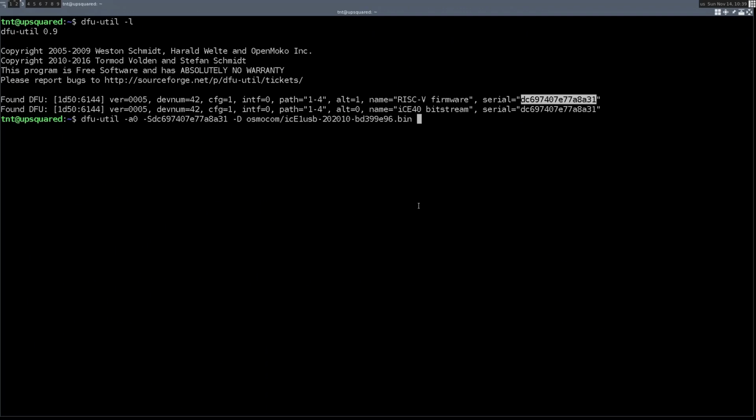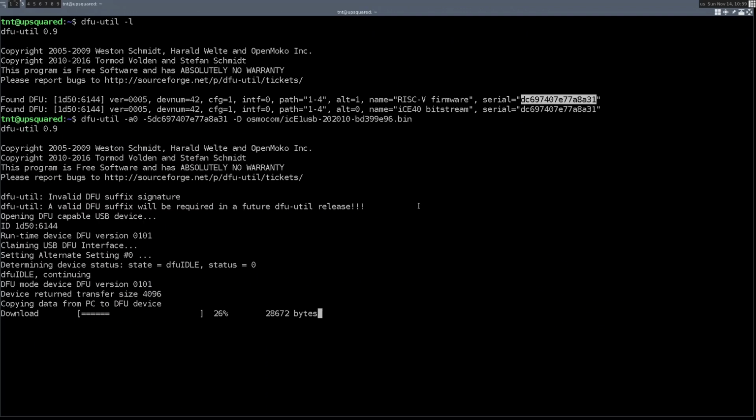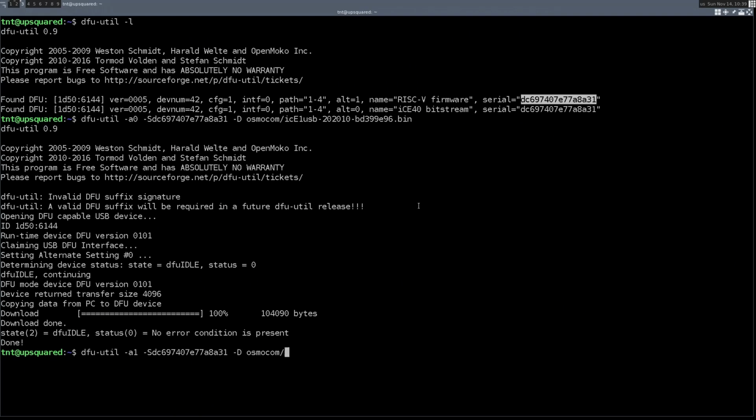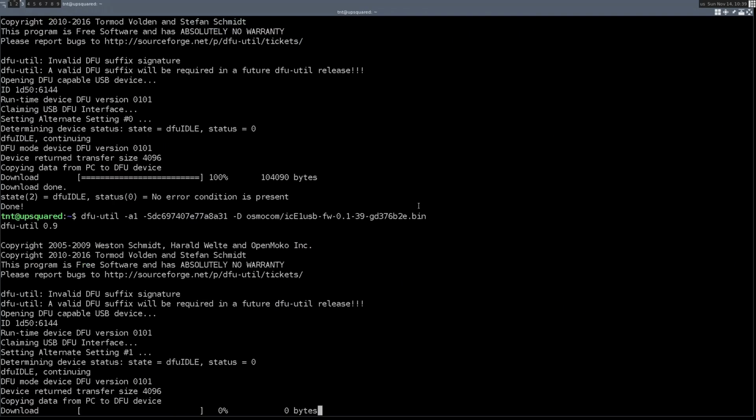Also, unless you know for sure there are no compatibility issues, both the gateway and the matching firmware should be flashed together at the same time, since different versions of gateway firmware might not be compatible with each other and might result in either the device not working at all or some weird behavior.